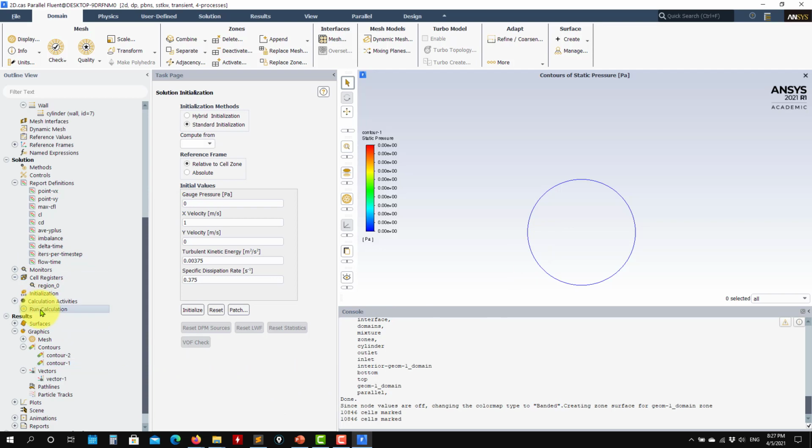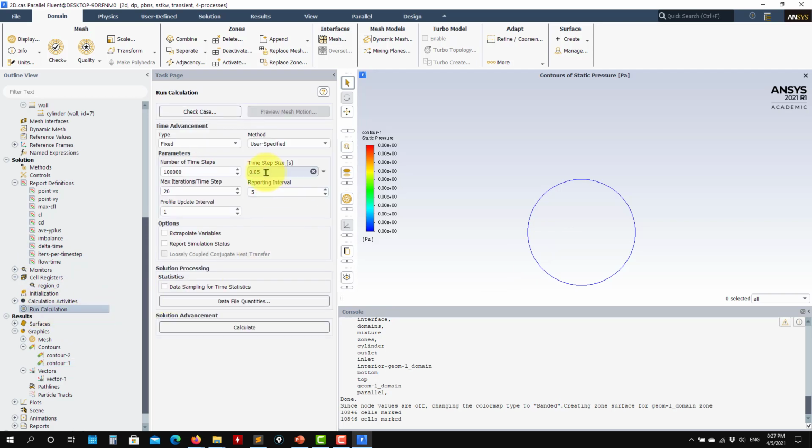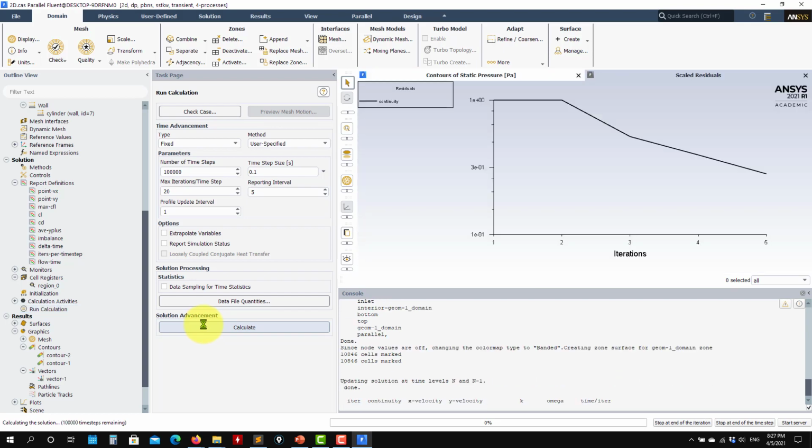So now that we have the uniform initialization, I will go here, I have the monitors, I will increase the CFL to 1. This will be something equivalent to 10. The time step to 0.1 and it will be a CFL of 10. Okay, you can compute the statistics. I don't need it, okay, I just want to show you that it will take longer. And it's running to 100 seconds. And let me press now here, calculate, and off you go.